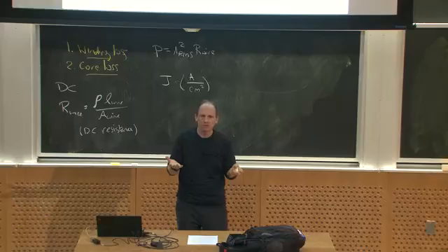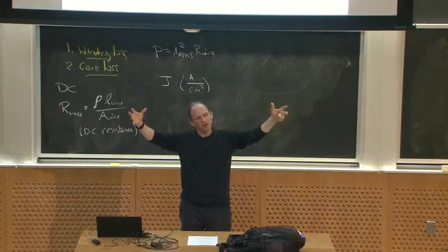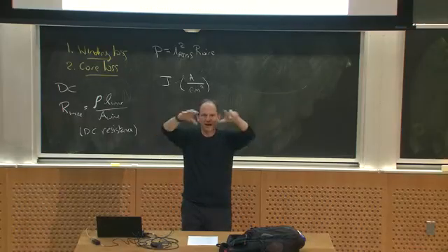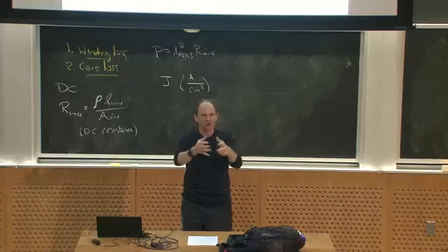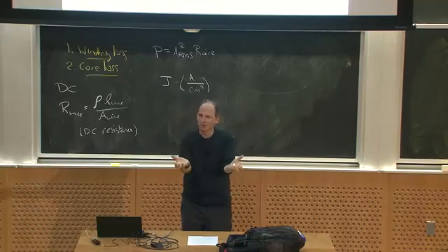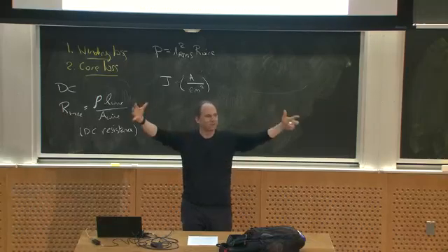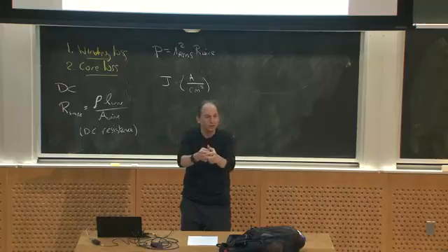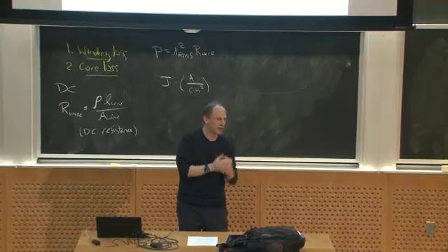And that number depends on size, right? If I have something really big, there's a long distance to get heat out. It has a very high volume to surface area ratio, because volume goes as the cube and surface area only goes as the square of linear dimension. So if you have something small, it's easy to get heat out of it. If you have something big, it's hard to get heat out of it. So typically the current densities you can use depend upon how big the thing you're building is. Smaller, you can use higher current densities.